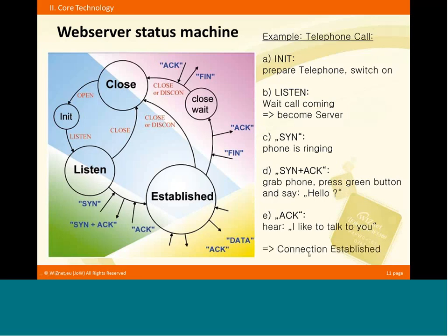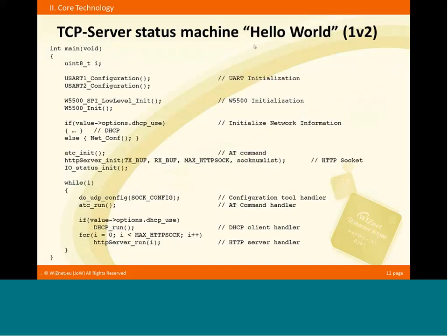Okay, once the connection is established, data can be transferred like memcopy. You copy the data you want to send into the internal memory and you give a command, send the data. And if data is coming in, the packages are unpacked and the raw data is in our memory and the MCU can access that data. That is a very simple read and write process. So I can show you a small TCP server, kind of web server.